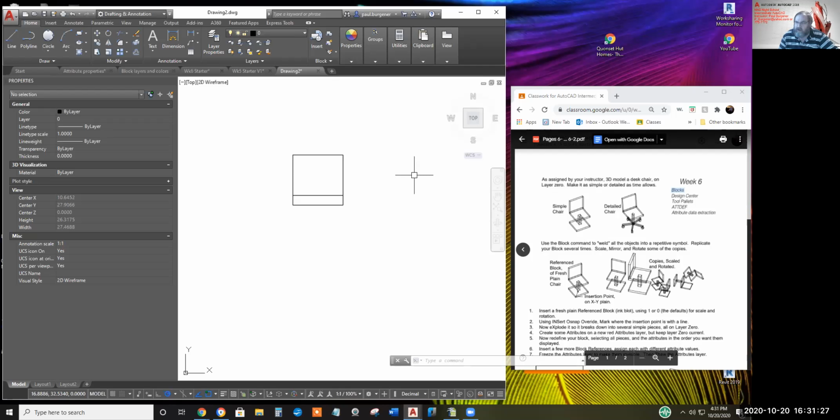It's at point X, Y, Z. It's at this rotation. It's at this X, Y, and Z scale. It's on this layer. Maybe a few other things, but if you array this, you build a rectangular array of this, say 10,000 by 10,000, you might end up with a 100 kilobyte file pretty fast. Making it into a block and then replicating the block 1,000 by 1,000 would probably be less than, I don't know, 30 or 40 kilobytes.